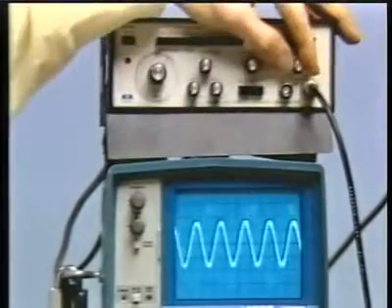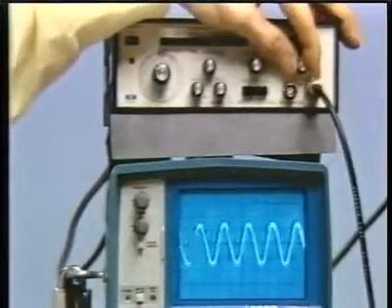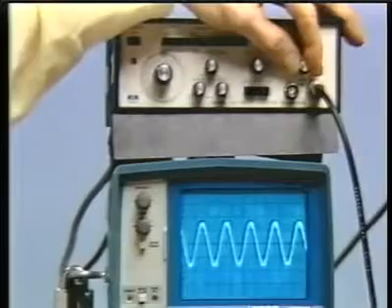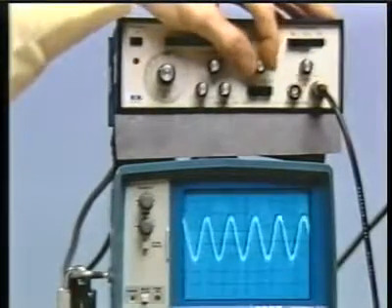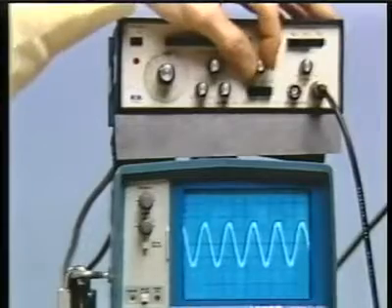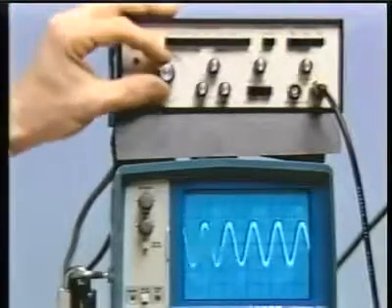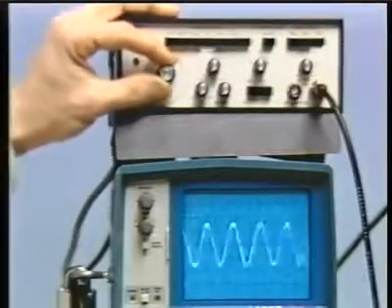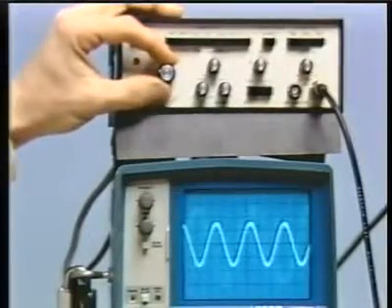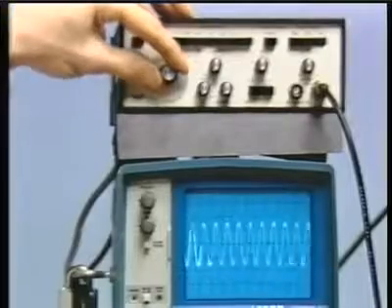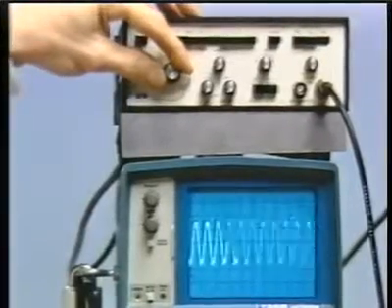By varying the amplitude knob, you can make the sine wave smaller or larger. The ear isn't too sensitive to that. By changing the DC offset, it simply rides on a different level. It's like putting a battery in series. And changing the frequency, you get a very perceptible change. At a lower frequency, it takes longer to sweep through a period. At a higher frequency, it takes a shorter amount of time.